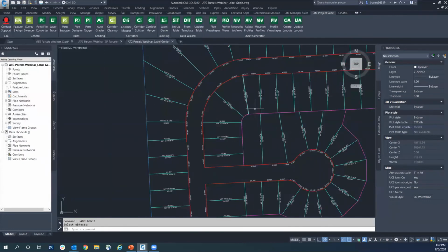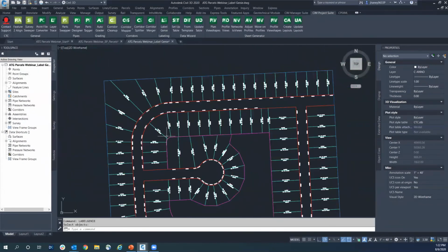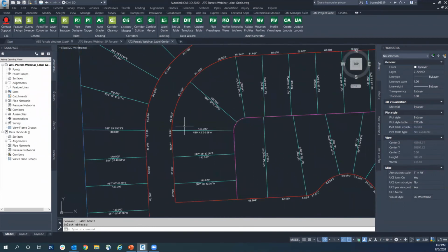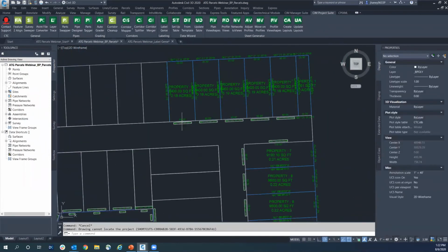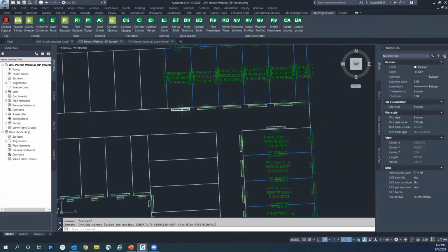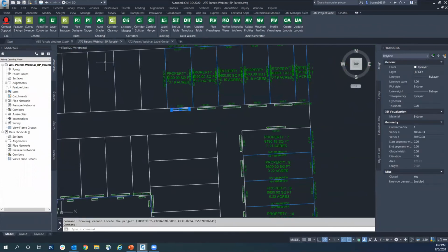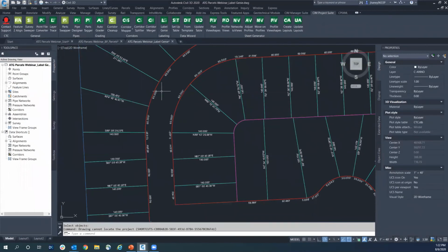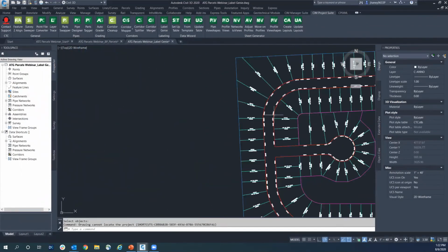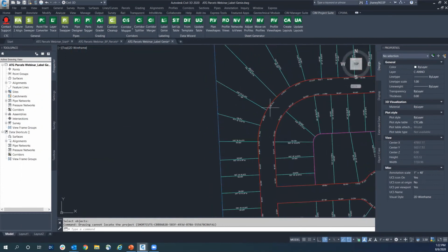And now it labels. Obviously, I've done plats before. I do not like to label things on the inside. If I'm doing this with parcels, like we did back here on this other one, and this was labeled out here, I would have to come in here and flip those, right? Well, we could have done that automatically from the get-go, but let's just go ahead and show you what it looks like after the fact with Label Genie.